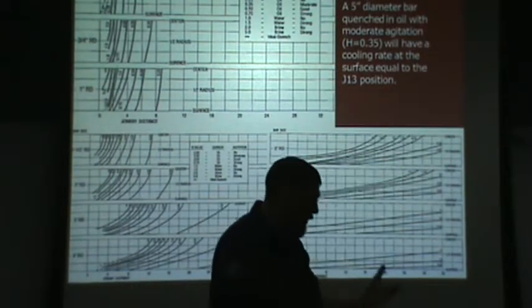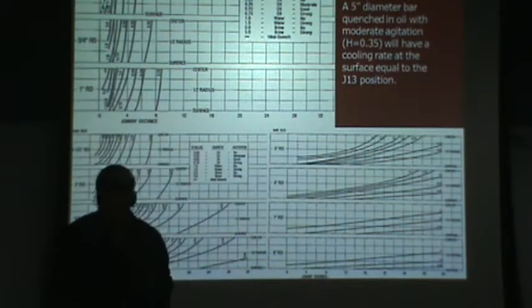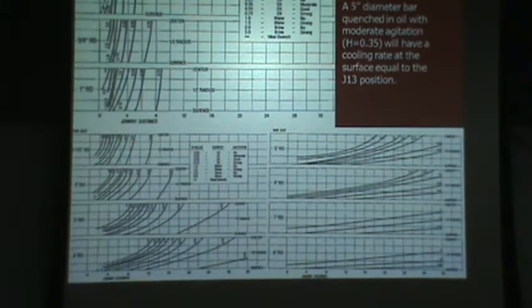It was published and is still available through the Timken Company. They've updated it from that particular copy. It's got all different kinds of information in it. Things like what's the typical composition of 5160 or 1080 or 4320, it's in there, along with compositions of lots of other elements. And then these curves, relationships between quench severity and geometry hardenability, that's where these come from.